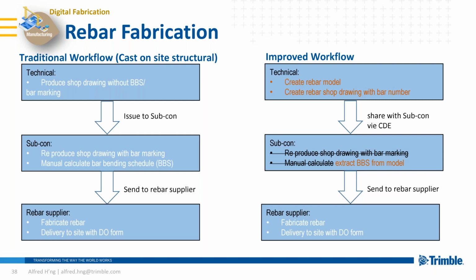On the right is the proposed workflow. At first, the rebar model needs to be worked out first, and the rebar shop drawing will be generated directly from the rebar model. And we will put this model and drawing into the CDE, and our goal is to get the model to carry trusted rebar information with enough accuracy, so that our subcontractor and our rebar scheduler can make use of the information and generate the BBS directly from the model. Yeah, that is our goal. Next, please.